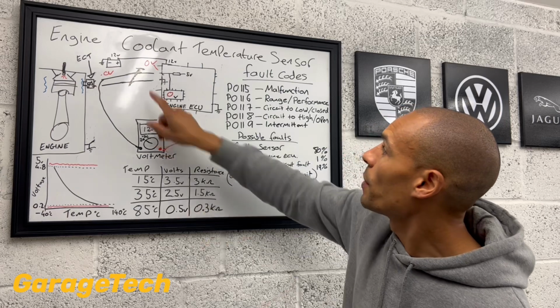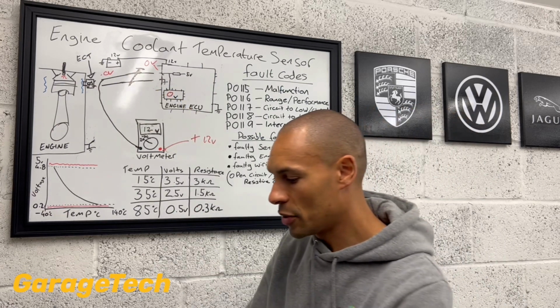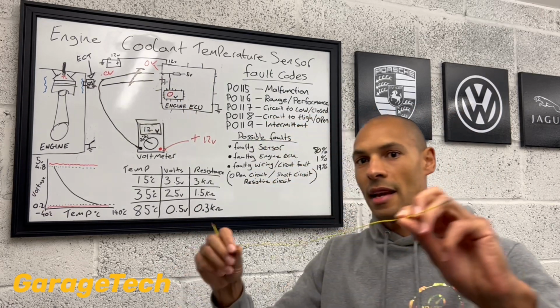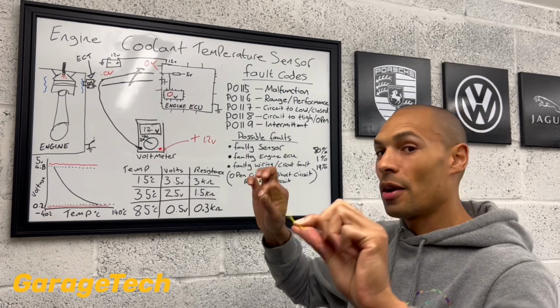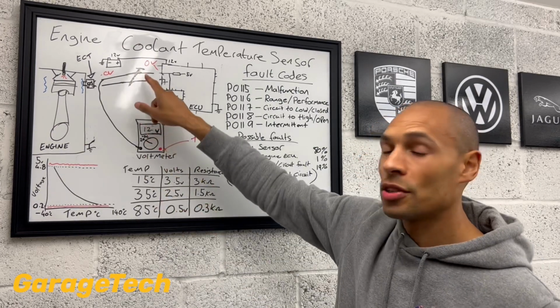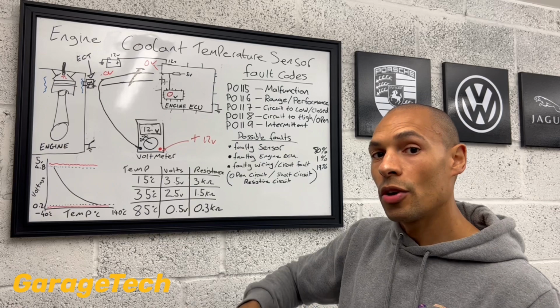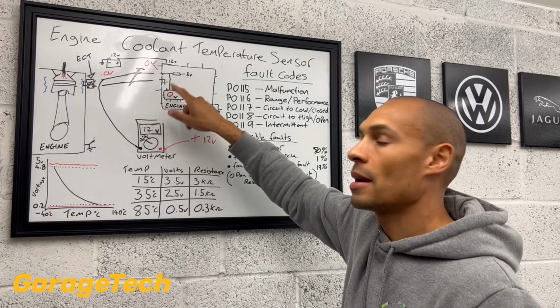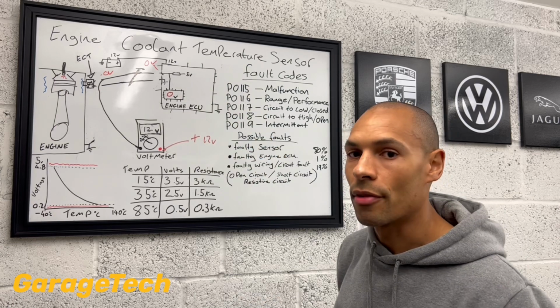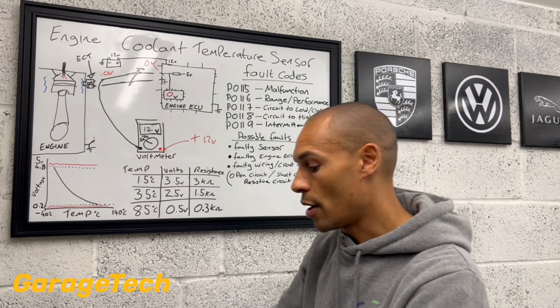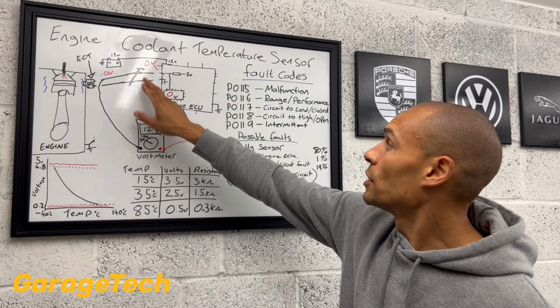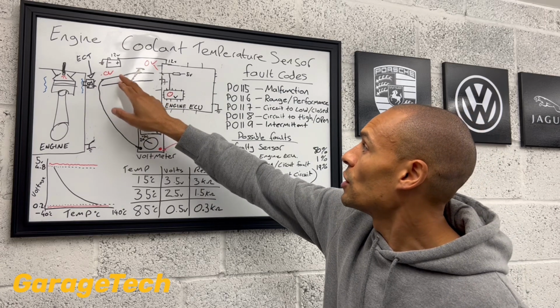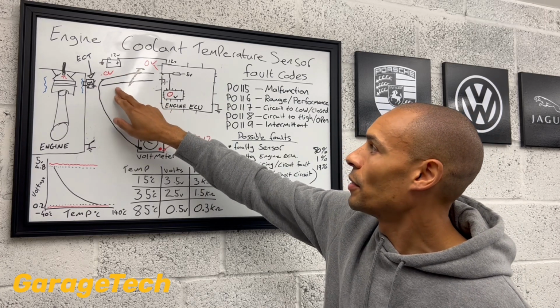I know that that piece of wire, that should be just a piece of wire floating in the air, as it were, I know that that wire somewhere is touching the body of the car, or it could be that it's chafed out onto another wire that goes back to maybe the engine ECU or whatever it is, somewhere else, or another earth. So they're just some of the checks that you need to do. That will give you an indication that you've got a short somewhere. You do exactly the same on the other wire.